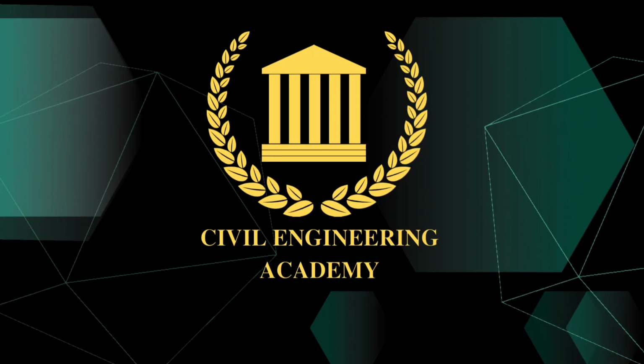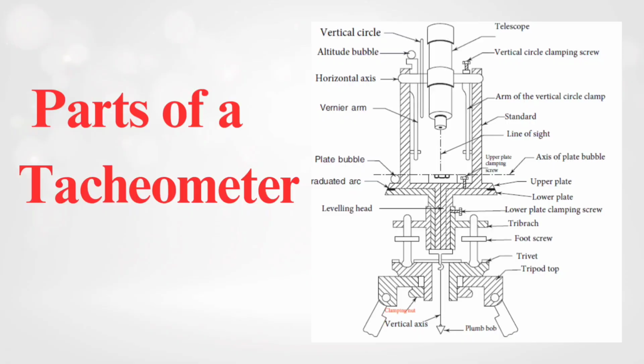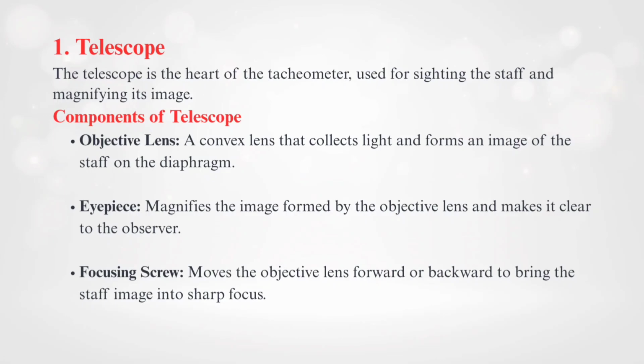In today's video, we are going to learn about the parts of a tacheometer. A tacheometer is basically a modified theodolite that helps us to measure horizontal distances, elevations and the differences in height quickly without using chain and tape. So the very first and most important part is a telescope. It is used for sighting the staff and magnifying the image so that we can read the staff clearly.